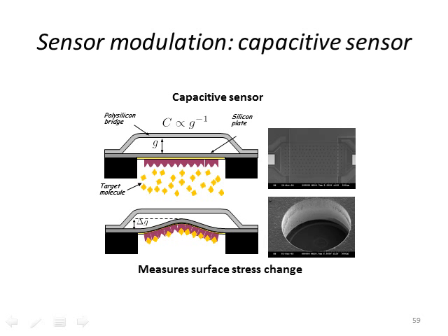I made these myself, and they are basically made from doped polysilicon and doped silicon, so these are highly conductive plates. We put this into a solution and let molecules bind onto one surface of this lower silicon plate, which induces a stress that causes the plate to bend. And when the plate bends, it changes the capacitance reading. Okay?